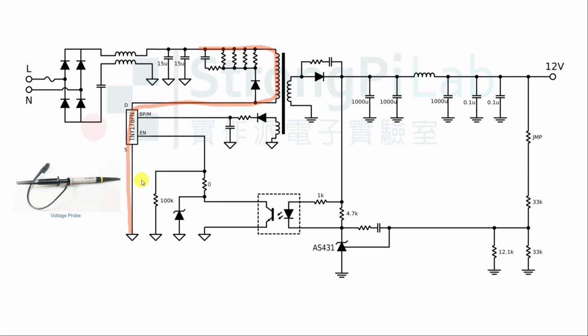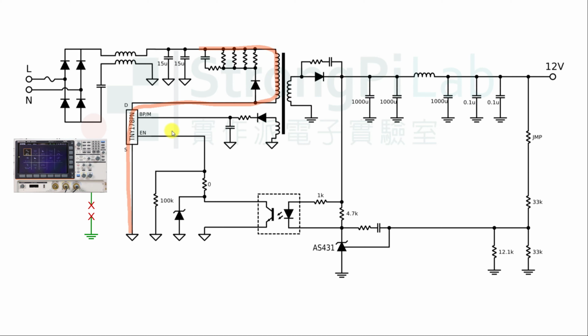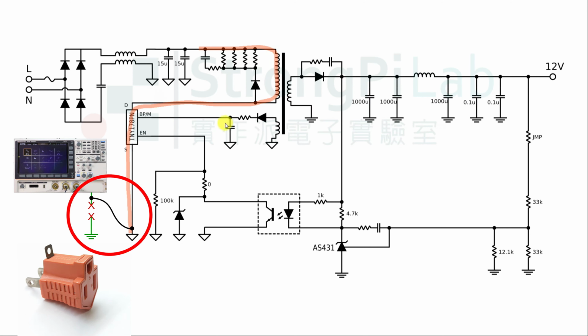It is tricky. All you have to do is cut the ground wire of the oscilloscope. A ground lifter can help you do this. Now when we connect the oscilloscope's ground to the hot ground, the scope's ground becomes hot ground. Then we can measure the VDS accurately. To accomplish this, we absolutely have to take some level of risk. Any exposed metal of the oscilloscope must never contact any cold ground. Otherwise the DUT will blow out.